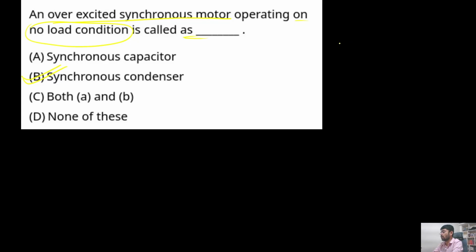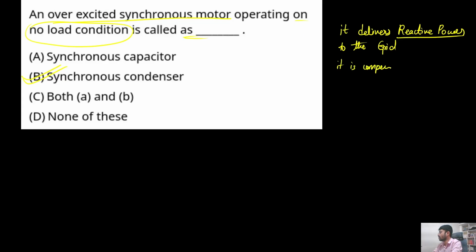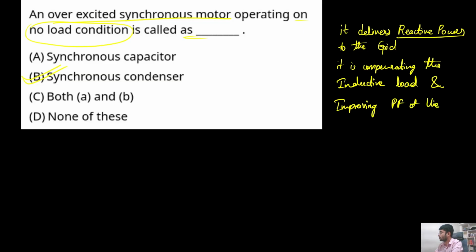Whenever a synchronous motor at no load is overexcited, it delivers reactive power to the grid, which means it is compensating the inductive load and improving the power factor of the network.